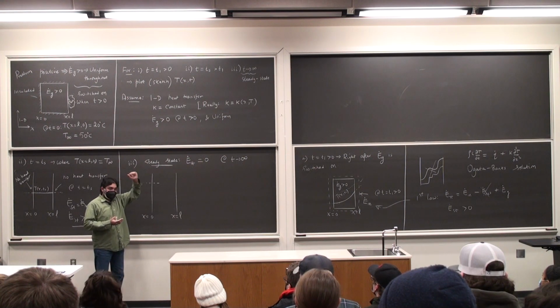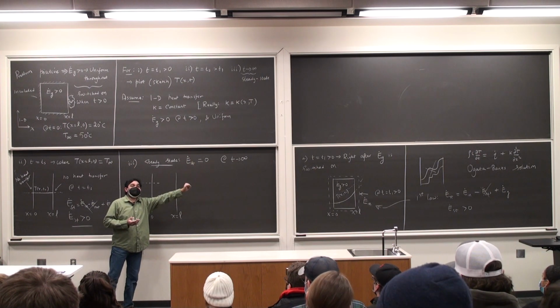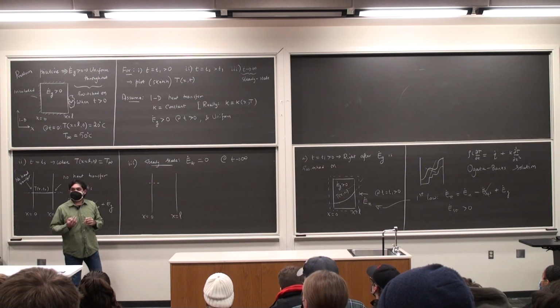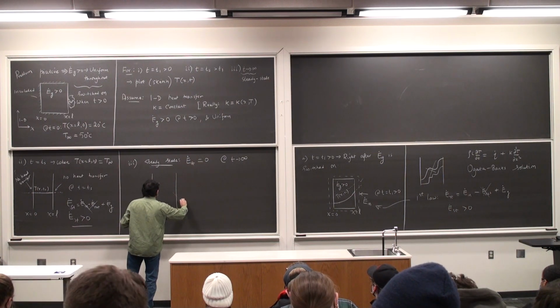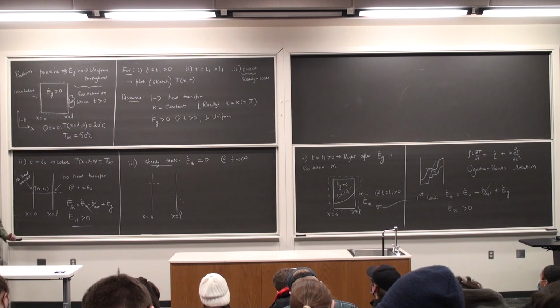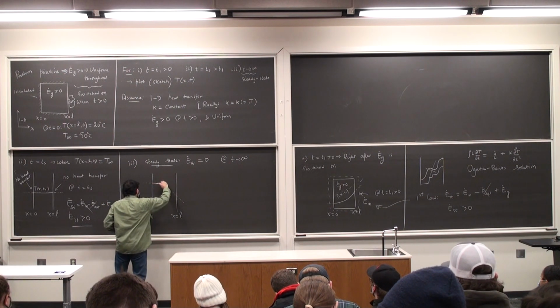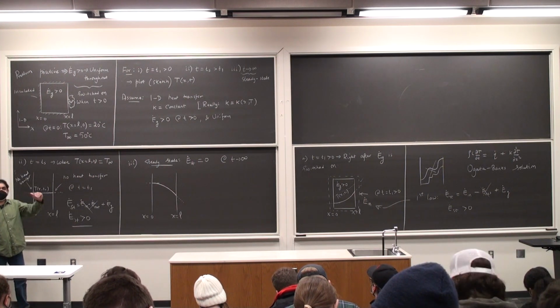There is going to be heat transfer taking place from the x is equal to L side onto the ambient, because we are now seeing that the x is equal to L side exceeds the ambient temperature. Okay, so the slope here is going to be negative. The slope at the x is equal to 0 side is 0, and we have a nice smooth curve. Okay, and so there is heat transfer out.